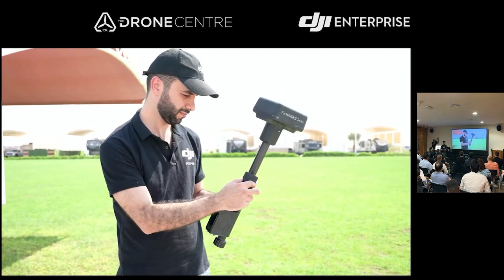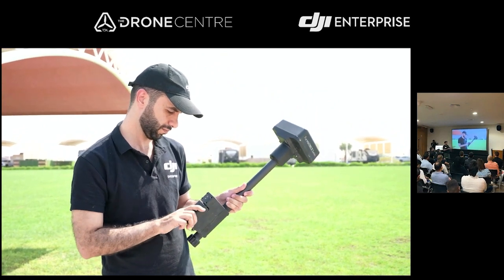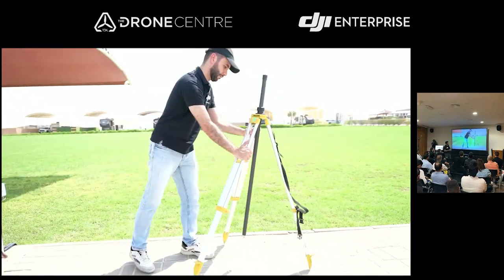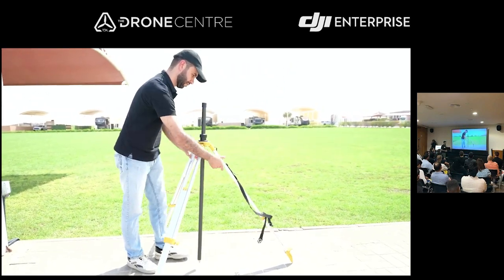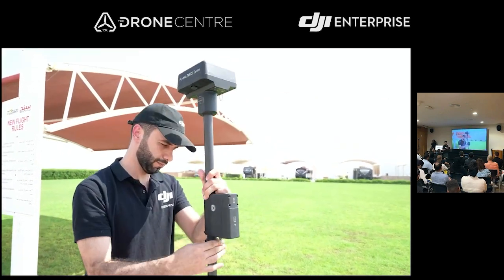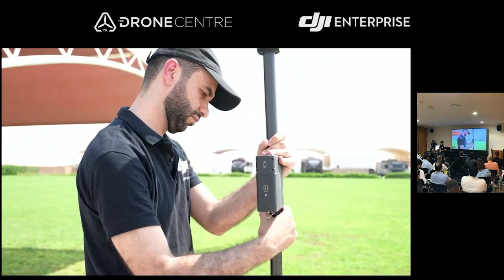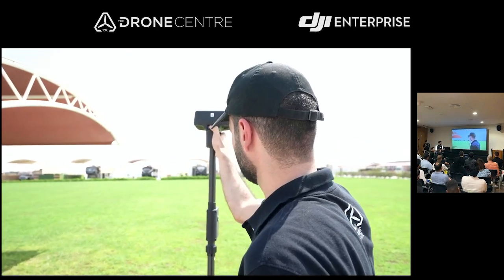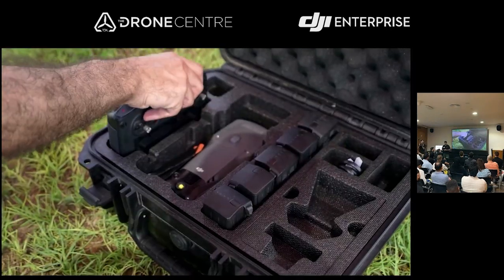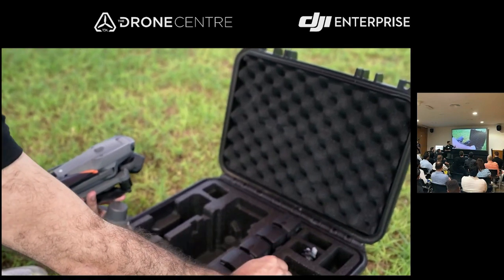First things first, we have to set up our base station, the DRTK. In any survey work, this is a fundamental rule. You might know that better. And we are setting up with the tripod because it should be stable. There is no margin of error when doing survey work. So we are setting up the DRTK with the tripod, and it comes with a battery inside. And we are using DRTK as a base station here in this region. You can also use a 4G based server.